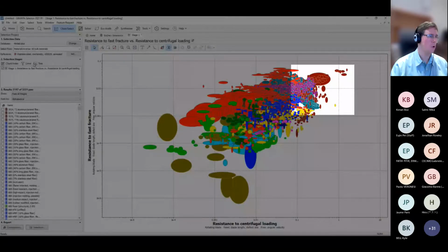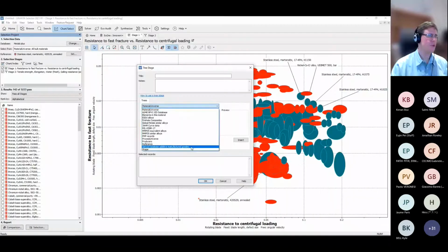We know there are certain minimum requirements, in terms of tensile strength, elongation, and environmental durability and wear. So we use these to eliminate a whole bunch of unsuitable candidates. Go back to our graph. You can see we're now down to relatively few materials out of the thousands originally there. And that's our reference material. There are better ones available, and they're all towards the top right.